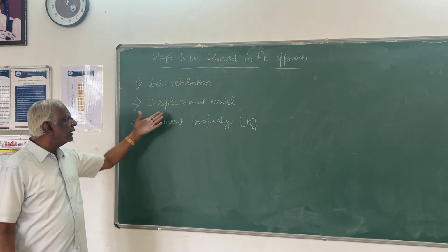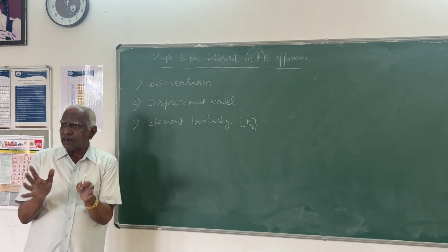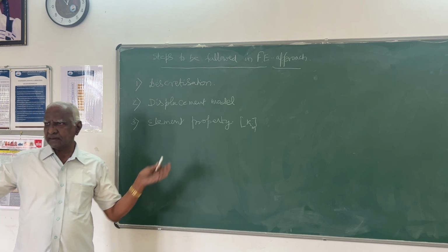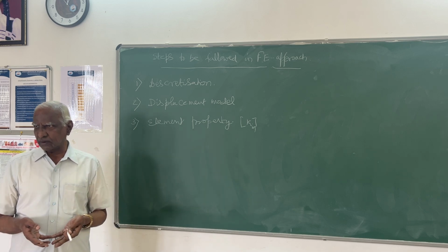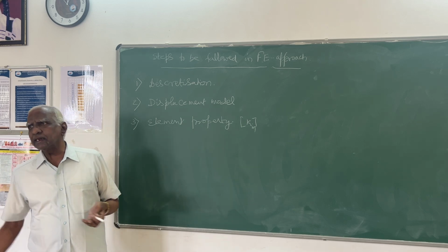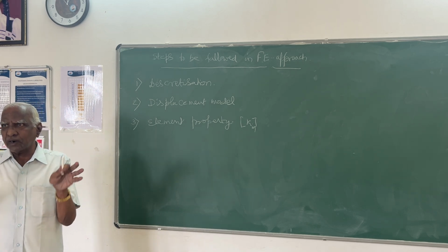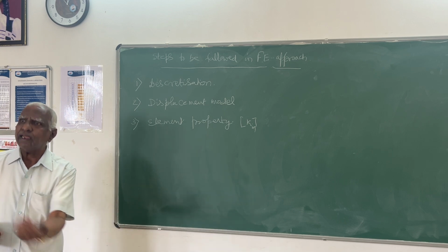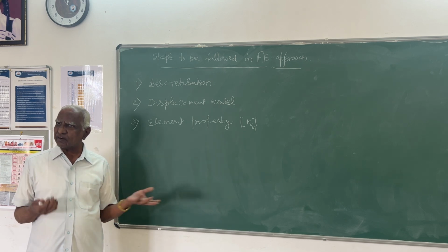Integral functions are used because once you know the strain and stress, you can use the simple equilibrium condition. That is the total work done by the application of the force, which is known. The total work done will be equal to the internal strain energy developed within the body, as long as the body or structure is in equilibrium. Total external force has to be equal to the internal stresses developed. That internal stress developed we have to estimate.